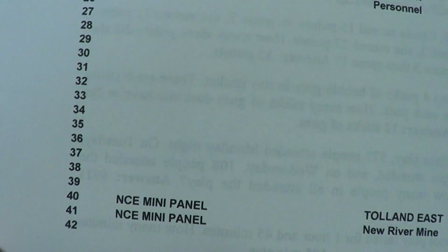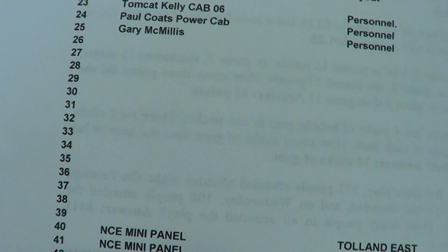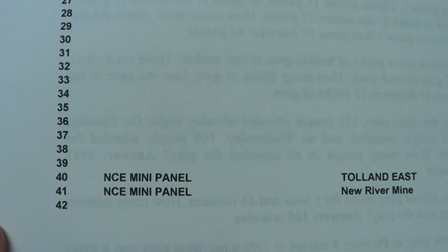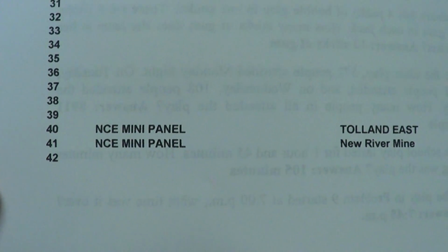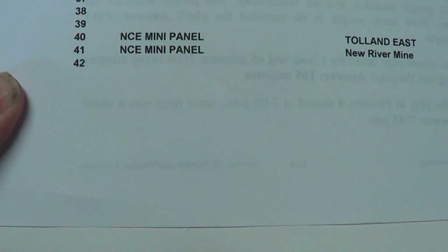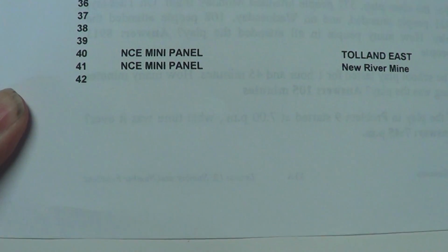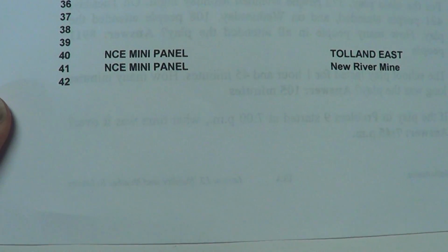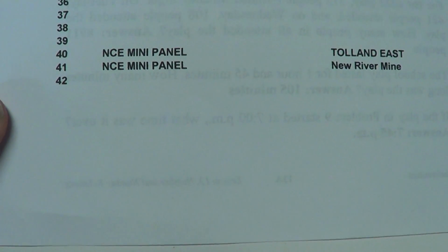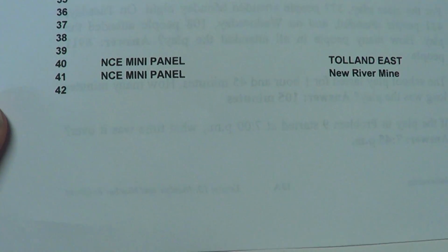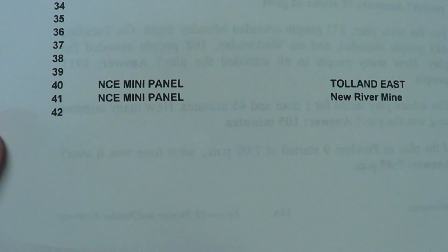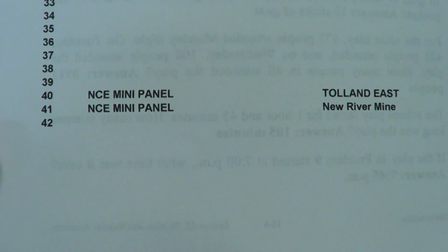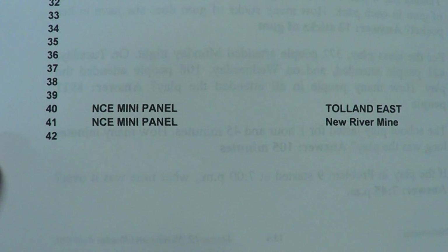Also, if you pan all the way down here, you get into some of the other things cab addresses are used for. In this case, there's too many panels. I didn't print it out, but if you went down into the 50s on this setup, 50, 51, 52, 53, 54, 55, and 56 on this layout are used for AIU-01s for block detection. This layout's all detected on blocks, so those also have to have a cab address.